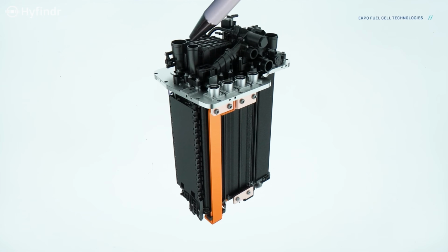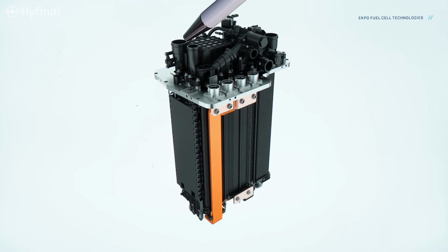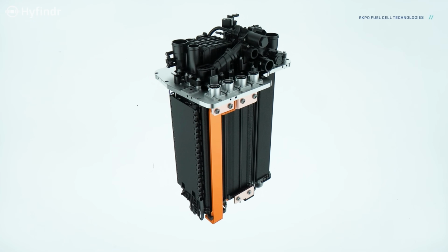Tell me, Joe, how do you then actually operate this thing? So what do you need to do to make this thing work well, get good performance, and obviously long life out of this? Certainly we need to supply both gases, so the hydrogen and the air, to the stack. The air in particular is humidified because the membrane needs water to conduct the protons. And then we also supply the coolant to the stack, and this is somewhat controlled with this MSA, what we take care about. So we preheat the hydrogen, we control the pressure of the hydrogen, for example, and we distribute the air and the hydrogen through the stack introduced by the MSA.